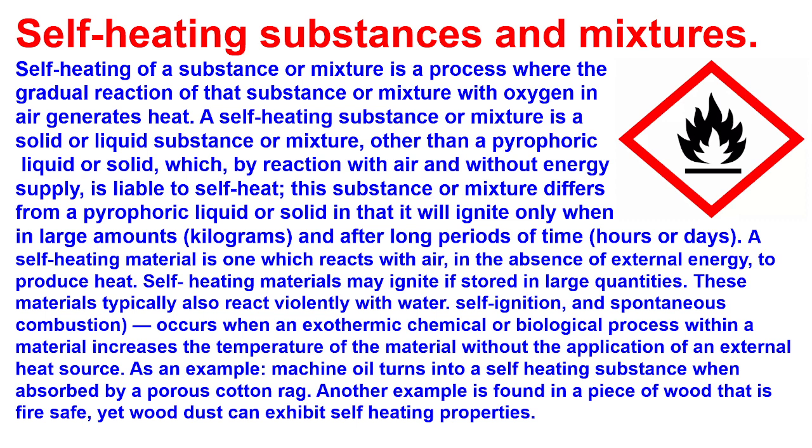Self-ignition and spontaneous combustion occurs when an exothermic chemical or biological process within a material increases the temperature of the material without the application of an external heat source. As an example, machine oil turns into a self-heating substance when absorbed by a porous cotton rag. Another example is found in a piece of wood that is fire-safe, yet wood dust can exhibit self-heating properties.